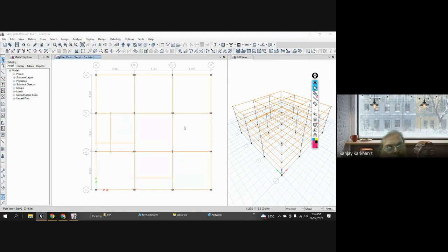Okay. Now what happened? Actually, you need it from this point to this point, but as your original was this, the same will be duplicated. Now, if you want to put it over here only, there are two ways. See, I will select this beam and I will divide the beam.